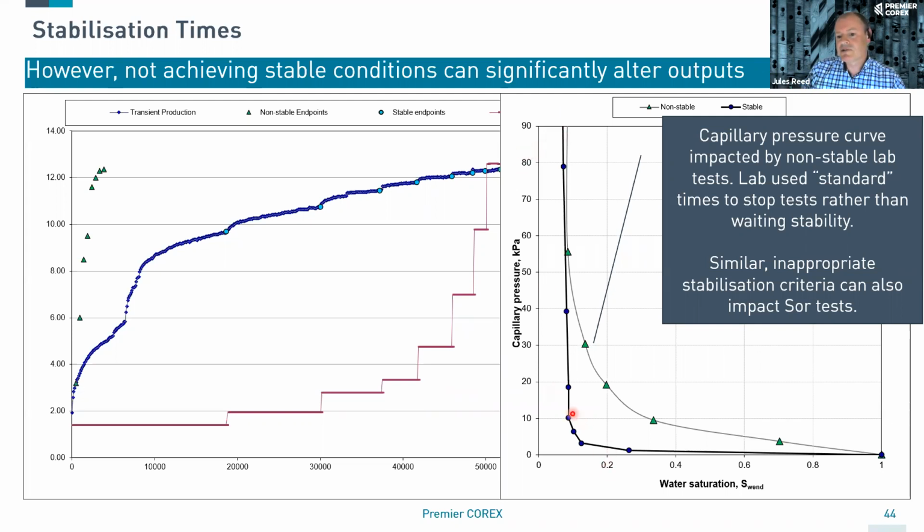But what we mean in the industry, usually what is meant by irreducible, is where the capillary curve is becoming asymptotic, or height above free water level in our reservoir is becoming asymptotic. By initial water saturation, that's often a laboratory term that roughly means the same as irreducible, but by laboratories who also may not like the term irreducible because it's not truly irreducible. If we had applied higher forces, we would have produced some more, which means it's not really irreducible.